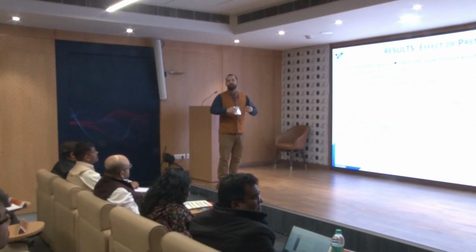That means there is only sufficient air to burn the syngas, but we are adding pilot fuel, so there must be excess air for the pilot. Globally, if you consider syngas plus the decane, then you will be probably too rich, but it's a small content, so perhaps 1.05. So it's more similar to what you can get with a gasoline engine. It's not like diesel.